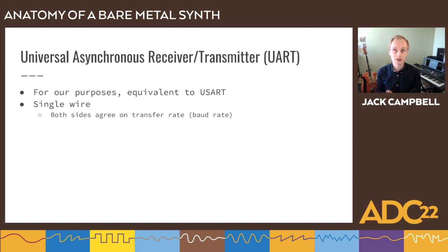And so the protocol is sensitive and not robust to differences in the rate of transfer. You need to be sending at a constant rate, because the receiving end will use that rate to determine when to read each bit. And the baud rate is bits per second.